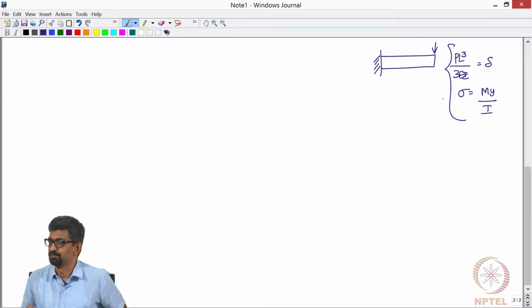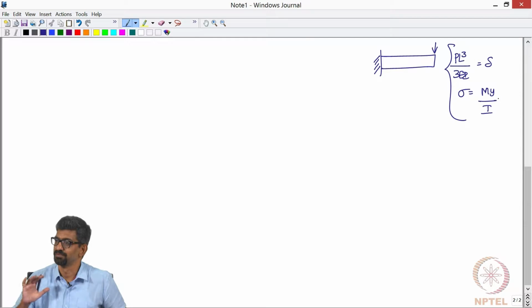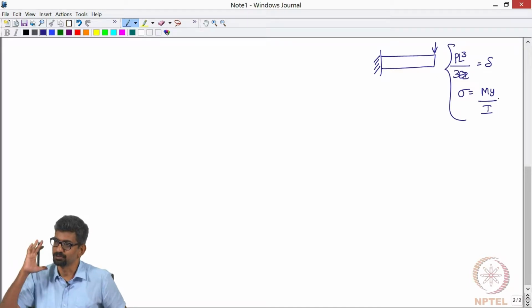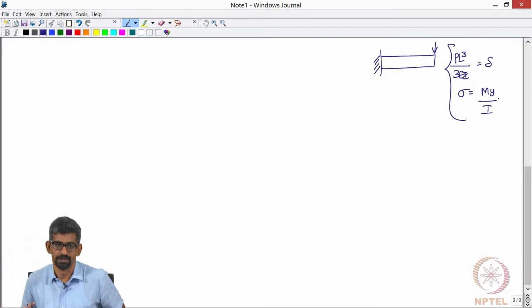But my problem requirement says that I need to meet some displacement constraints, or I need to meet some stress constraints, and obviously our goal is to reduce weight in this case, or it could be the other way around. I want to reduce stress. You are building a space structure, you are not worried about cost, you are worried about weight though. So, material selection could be the highest material that you can build.